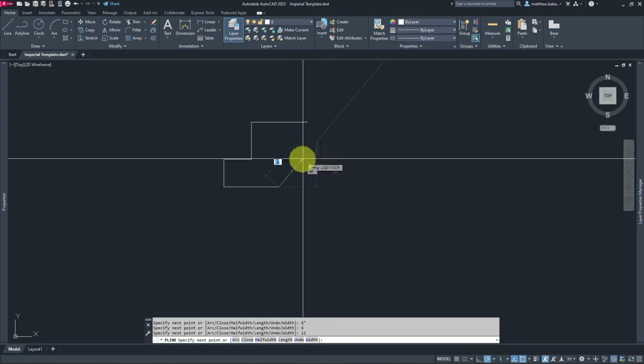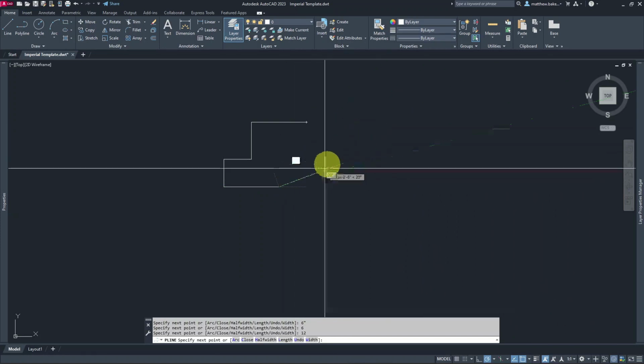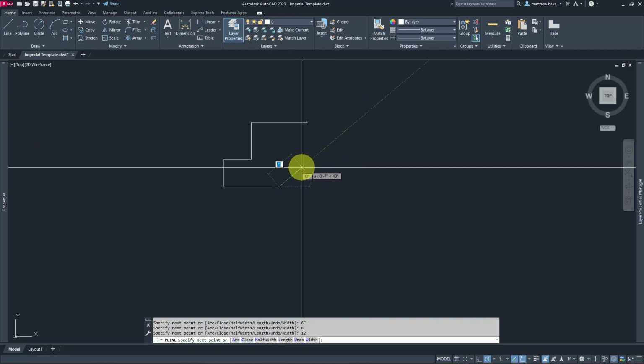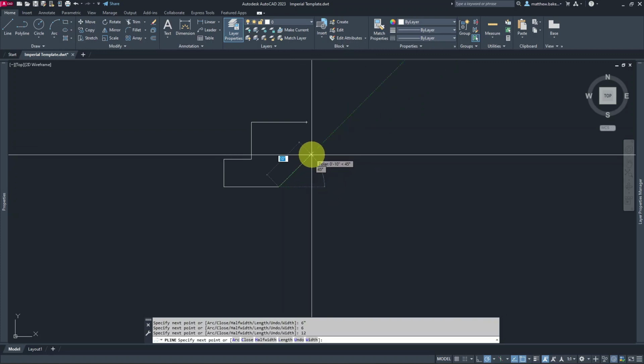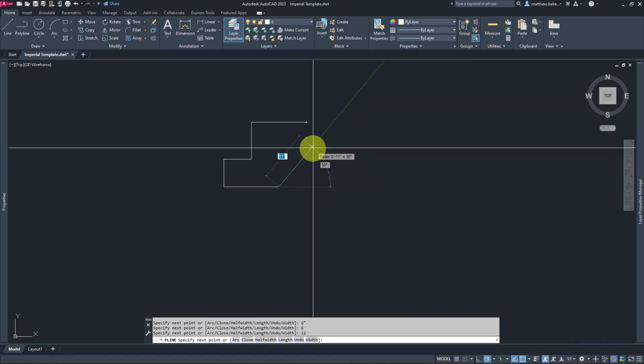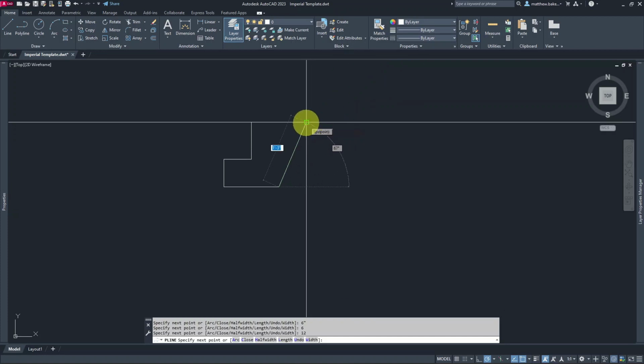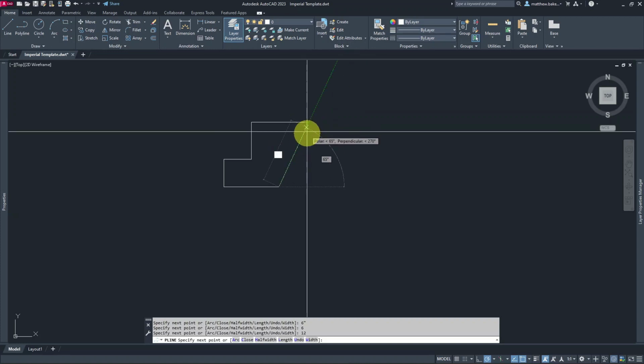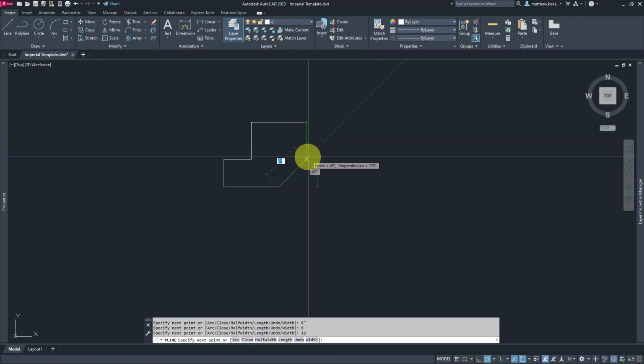And then now we know this line is at 45. So again, Osnap, having all the Osnap settings on, you'll see how handy it is here, because there's my 45, but where do we stop? So we're going to pick over the end point, which was actually our start point. So once we hover over that and then bring our mouse down, there we've got 45 degrees, and we're also in line with our start point. So it's going to lock on there.